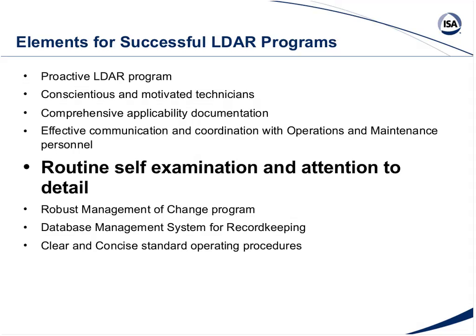Again, we're only as good as the person out in the field doing the work. And that's not just our technicians. That can be our operations and maintenance personnel. It can be your process engineers who are walking through. It can be your auditors. Anybody who's interacting with the equipment outside has the potential to be made aware of a potential leak, because we still have AVO leaks, those audio, visual, and olfactory leaks, that we have to watch for and document and maintain. We have to have documentation.